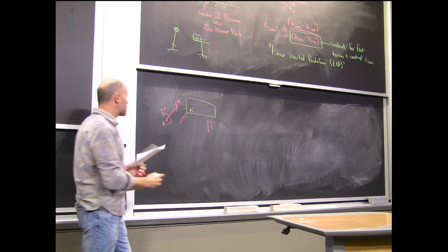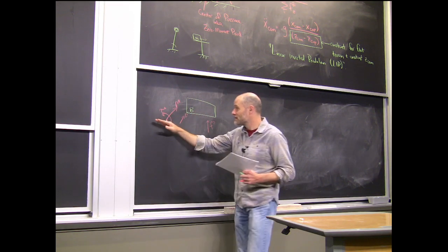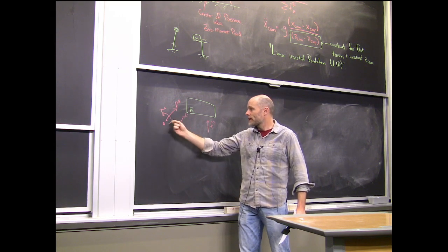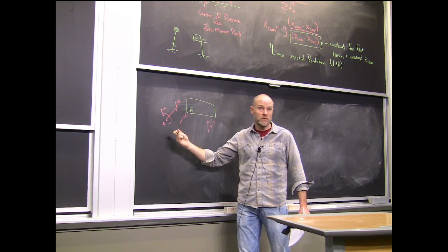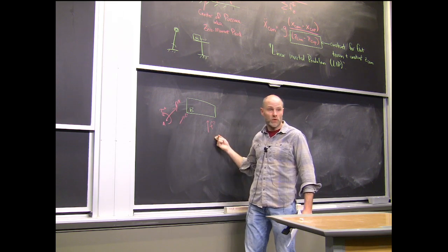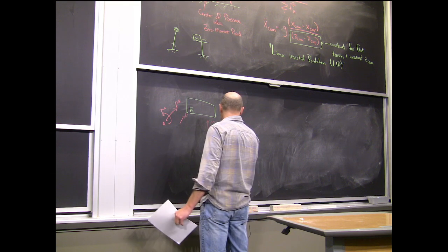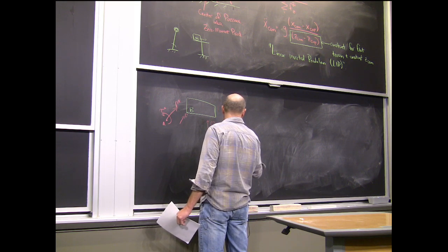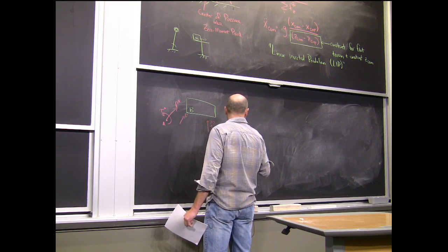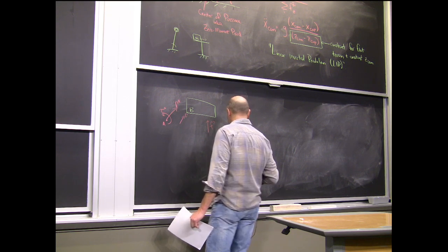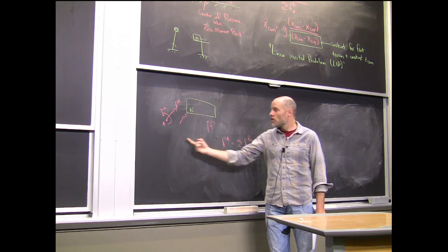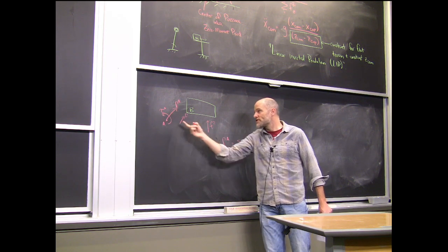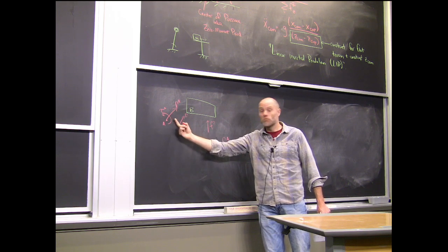There's actually an entire line of possible places you could pick where the force component is non-zero, but the torque component turns out to be zero. Any point where the summary of all these forces has zero moment required to describe it is called a zero moment point.